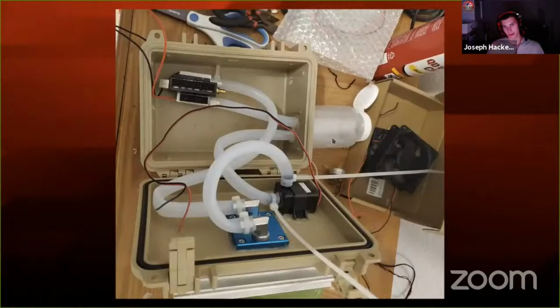So right here in the center, we have this bottle that's on the side, and that's my reservoir. You kind of need a reservoir for this to work because the pump has to be primed. It won't really create enough vacuum to suck water through it without already having water in it. So you have to have a little bit of a reservoir of water with both of the hoses submerged for this to work. Otherwise, there'll just be air in there and it'll just sit there spinning with air. So what I did is I put this little medicine bottle on here and fill it with water, and then you can tilt it around and get all the bubbles out.